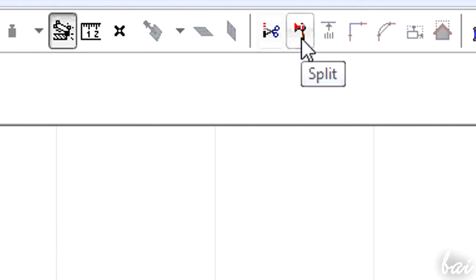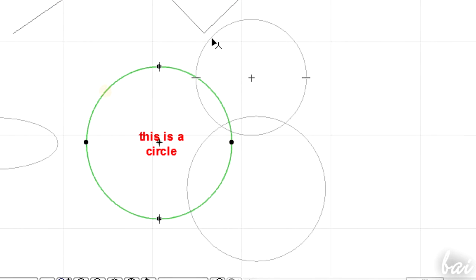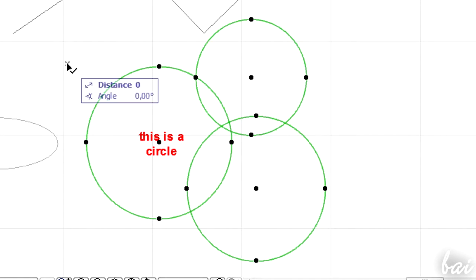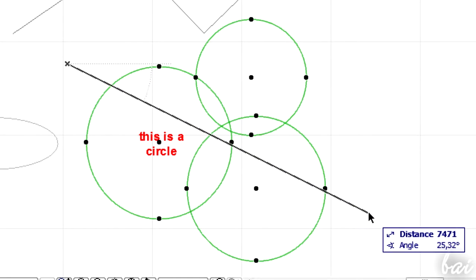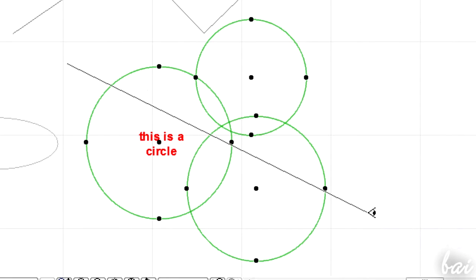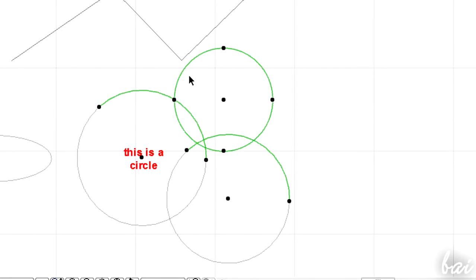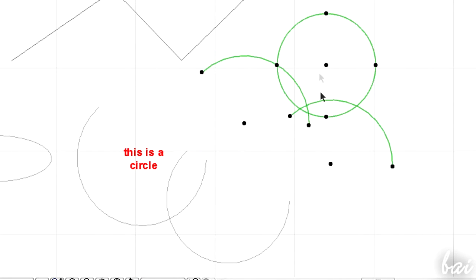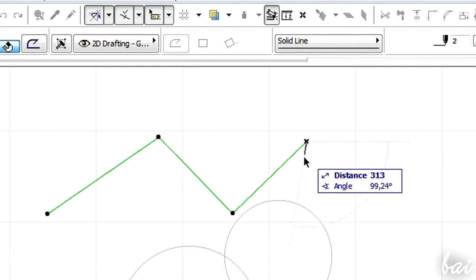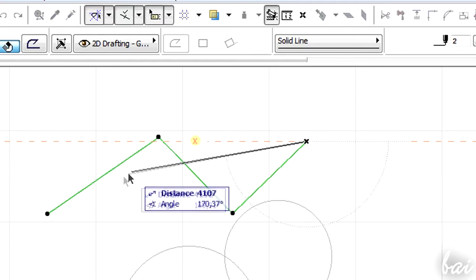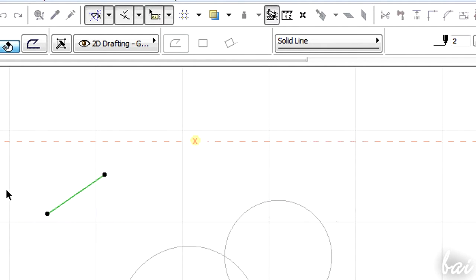The Split button is used to cut an object or a group of objects in two, without changing anything of the original shape. Select first the objects, click on a point and drag a line. The objects will be cut where this line intersects the object selected. The eye is simply used to quickly select the side to consider in your next step. Adjust works exactly the same, but with the difference that the objects are not split, but one of the two parts is completely deleted.